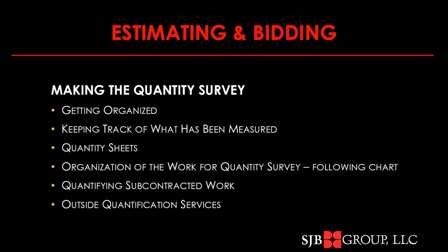In quantifying the subcontractor's work, I recommend that you quantify the subcontractor's work, even though he's going to give that to you later. Some of the reasons for that: you may recognize when their quote is out of line. It helps you check that the subcontractor's proposal covers everything.